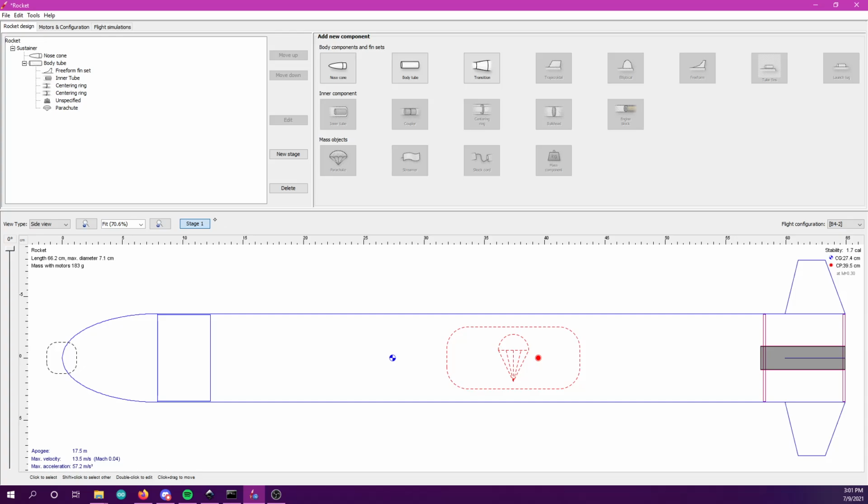Usually for TARC, we start off with our design parameters, our requirements that are handed down to us by the people running TARC. We get a rule book, and we have to base our rocket design off of the requirements in the rule book. Right now, our requirements are that we have 2 eggs horizontally mounted within the rocket with 2 different body tube shapes, so 2 different diameters.